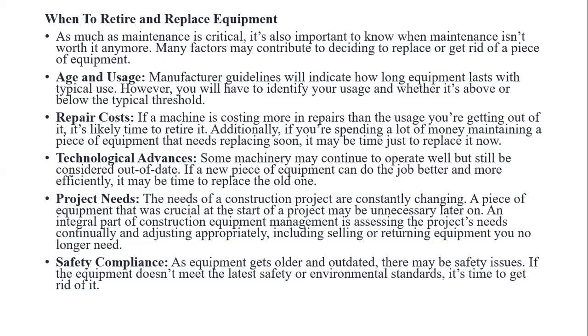At that time, we have to go for an alternative, and there are different factors to be considered before discarding any machine, namely age and usage, repair cost, technological advances, project need and safety complaints.